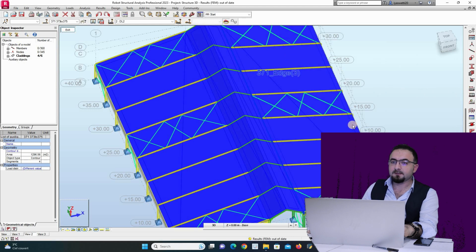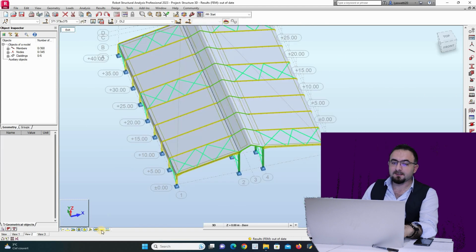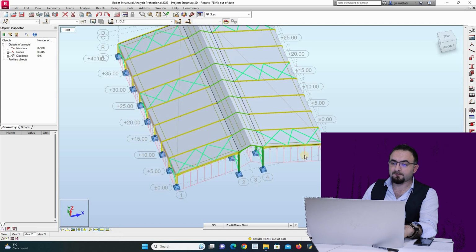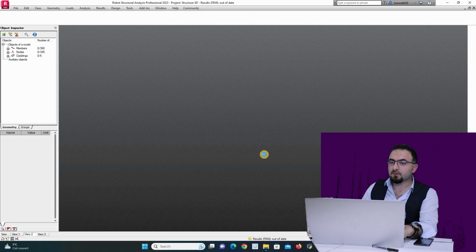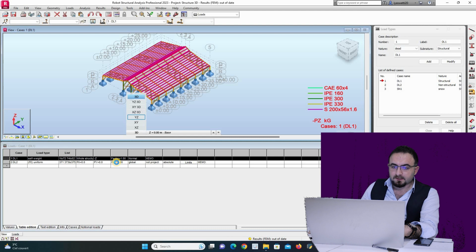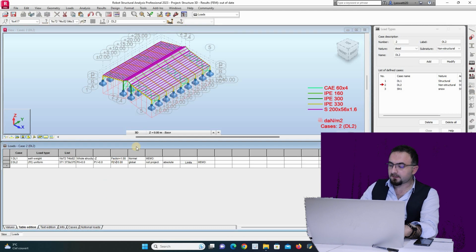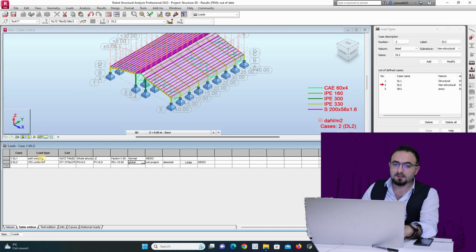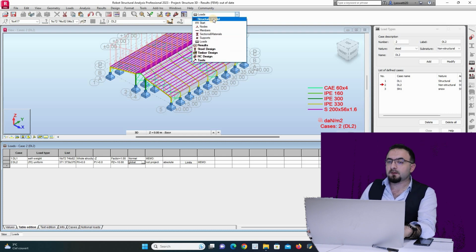As we can see, the load is in the other direction, because I did not add the minus sign to change it. So I can add minus here, and we are okay. So we have self weight, we have here uniform surface load, and we have all the elements. It is not projected, this is just for the snow.